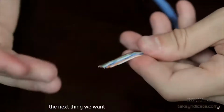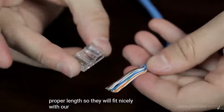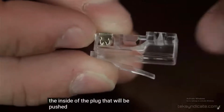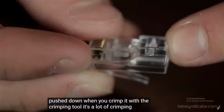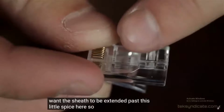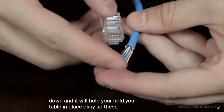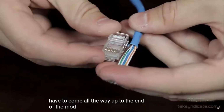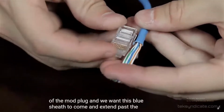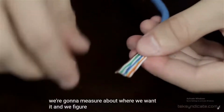The next thing we want to do is cut back the conductors to the proper length so they will fit nicely with our modular plug. There's a crimp on the inside of the plug that will be pushed down when you crimp it with the crimping tool. You want the sheath to be extended past this little space here, so it will get crimped down and it will hold your cable in place. So these conductors have to come all the way up to the end of the mod plug, and we want this blue sheath to extend past the crimping space that's right here. So we're going to measure about where we want it, and we figure this length is good.